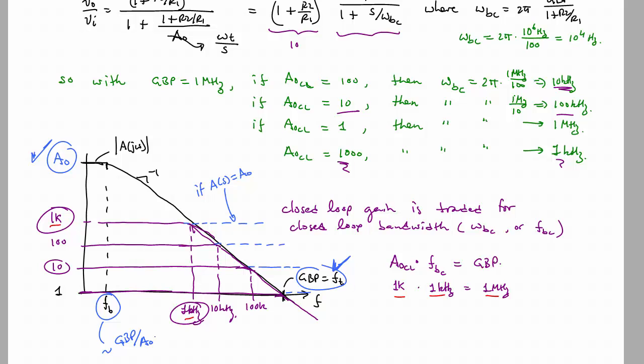One way to measure it is, let's say that you design a non-inverting op-amp circuit with a gain of 100, so this guy right here. Before this lecture, you'd expect that gain of 100 to extend out to excitation frequencies beyond 10 kilohertz. What you know now is that at some frequency it's going to roll off.